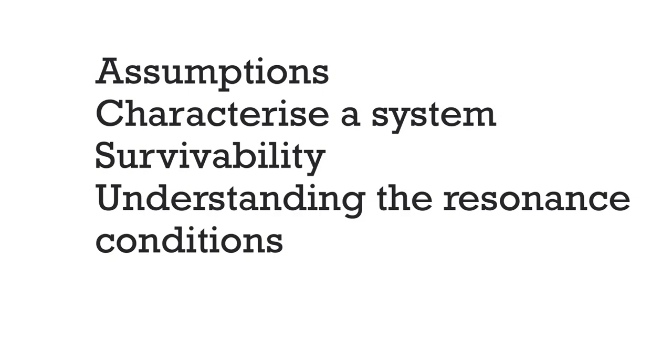The other parameter which is of key relevance in the modern era is that the average RPM, the average rotating velocity, of most machine components is on the rise. We can see a lot of machines, turbo pumps, operating at very high RPMs. Understanding the resonance conditions will help us prepare for the worst conditions, because we know when a particular resonance can happen. Moreover, the systems sitting close to our system of interest can be designed accordingly so that their resonances are separated by sufficient margins.